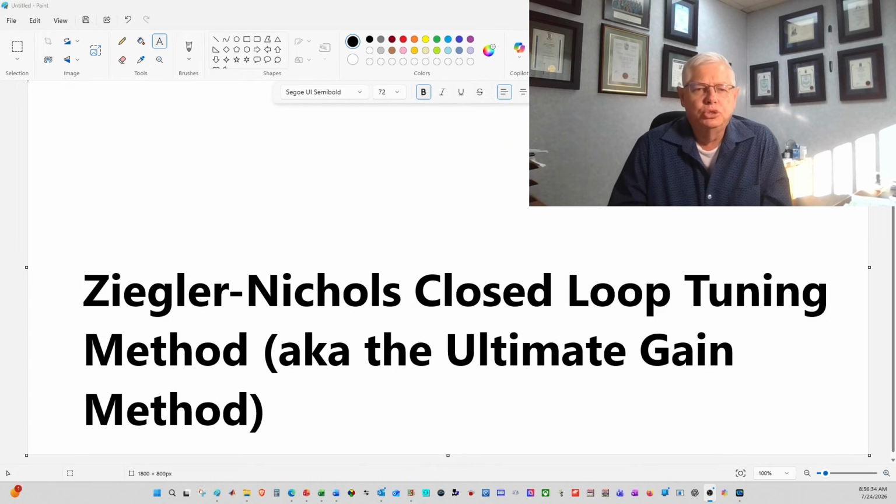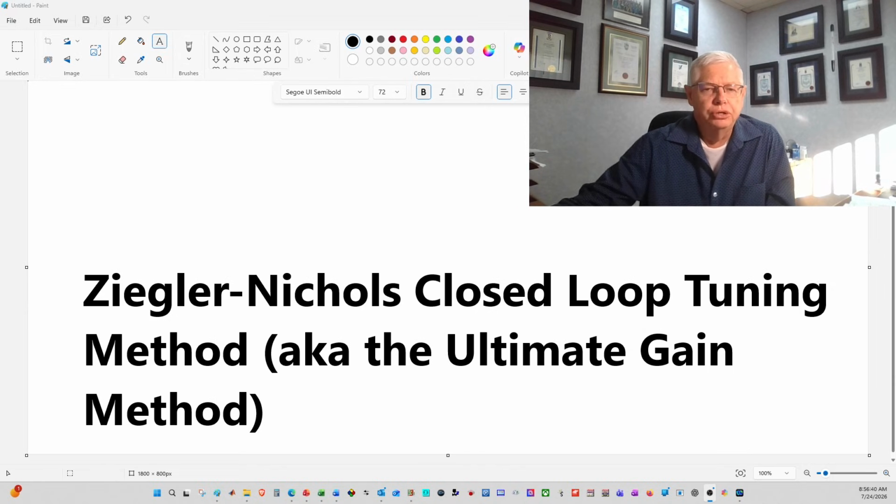Today we're going to do a brief video on the Ziegler-Nichols closed loop tuning. It's interesting that it has an alternate name, which is the ultimate gain method. This is a wonderful process tuning method that you can use in cases where you've possibly got a process that is integrating, and we would have dealt with that in an earlier video, or else a process where you are allowed to put the controller into manual and make the various adjustments that are required.